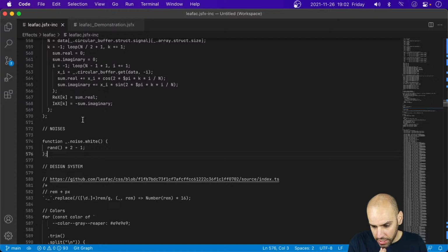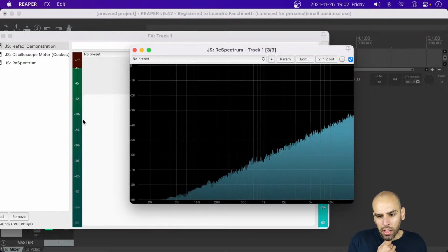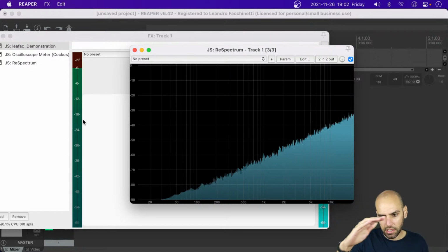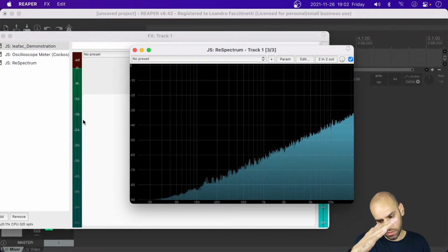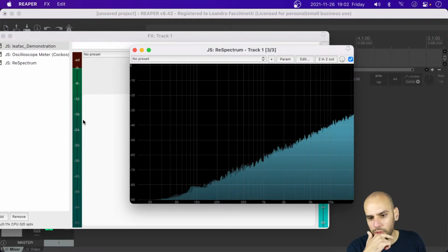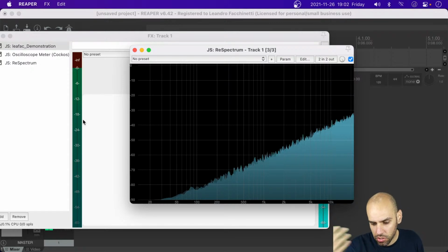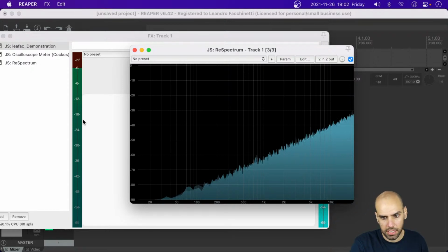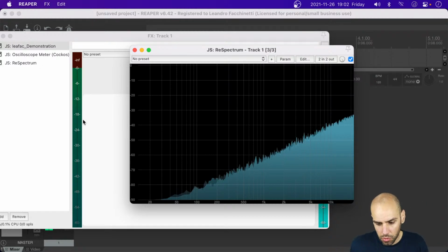Bo is asking, so it's basically a low-pass smoothing. Well, sort of. It's not a low pass in the sense that there will be a pass band and a reject band. It's more of a tilt sort of thing. So you may think of a tilt EQ kind of thing, but it's not a low pass. Usually a low pass has a pass band, a reject band. That's not what is happening.